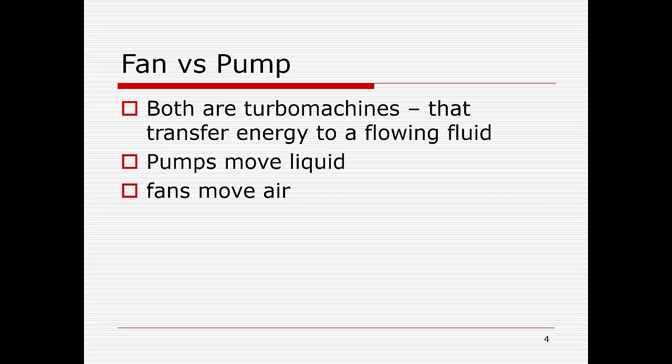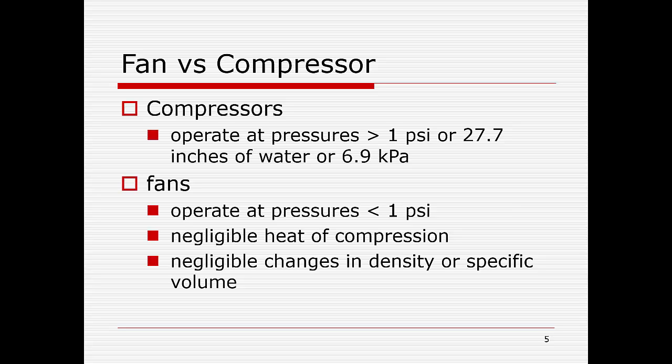Like we said, we studied pumps before and now we are studying fans. What's the difference? Basically, the pump moves the liquid, whereas the fan moves the air or gas. Okay. So what's the difference between the fan and a compressor? The compressor typically operates at a much higher pressure, whereas the fans we are going to consider operate at a very low pressure. For the purpose of the fan, we are going to assume that the air is incompressible. What that means is the density does not change.